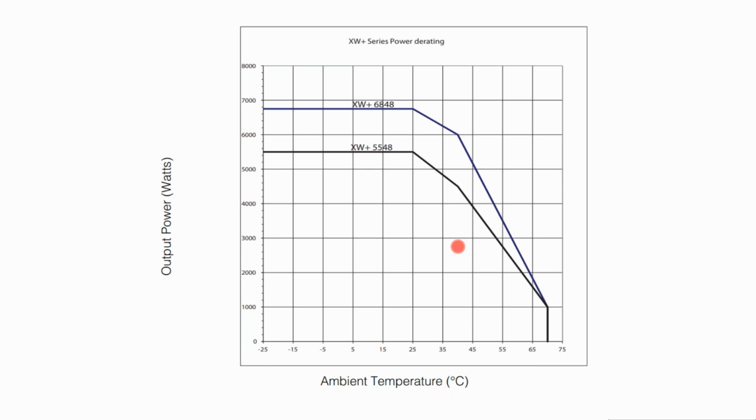It's more like they're going to start freezing around 14 or 15 degrees Fahrenheit. And unlike lithium ion, which has severe temperature issues, lead acid can take a little bit higher temperature. So you get a wider operating temperature range with lead acid, but that doesn't mean regulating the temperature of the battery isn't a good idea.